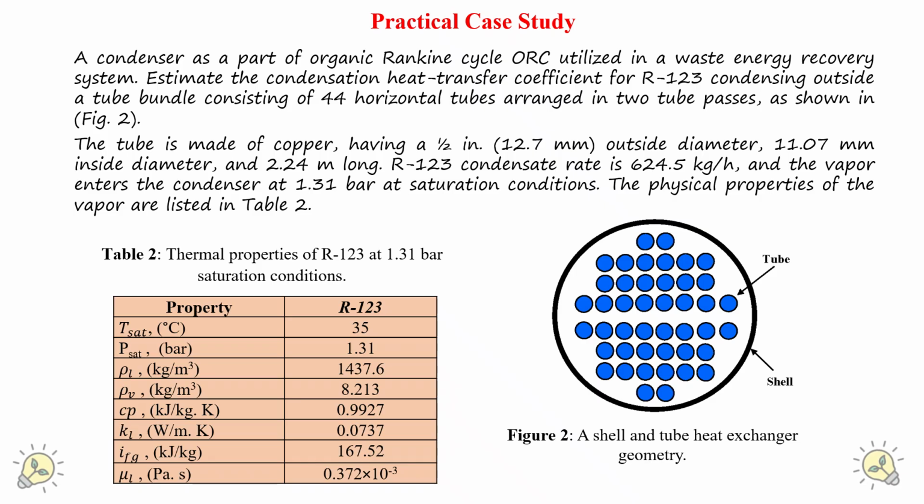Of course, table 2 shows the physical properties, starting from saturation temperature of 35, and we have the liquid viscosity at the bottom row as 0.372 times 10 to power minus 3 Pascal second. And we will use these thermal properties in the solution of our example.